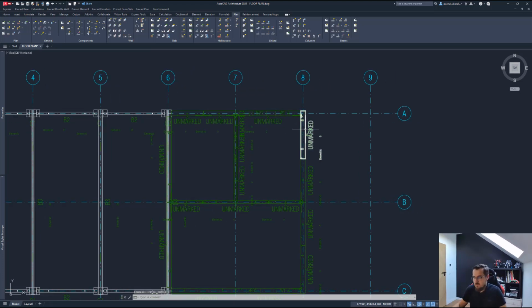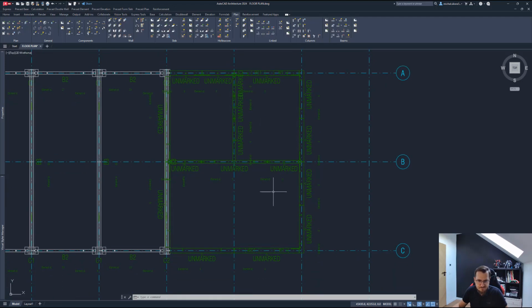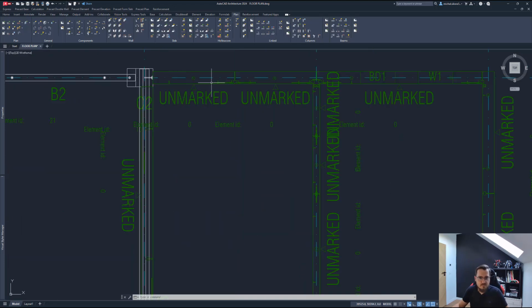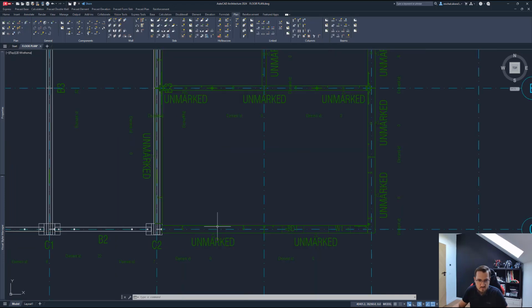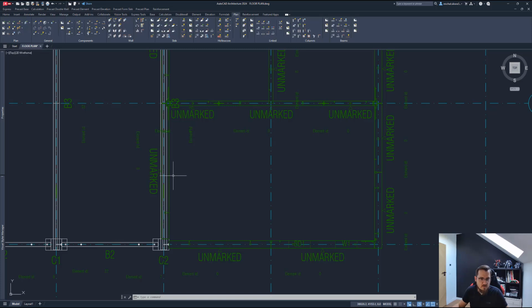What I now want to do is show you the panel thickening, because I want to place some slabs and I want to place them on some panel thickenings. So let's do that. Maybe in this section here. Now too many walls. So let's maybe do that here. Okay. So what I'll do here is I want to create a panel thickening. So I'll just click on this, sorry, not this one, draw panel, click thickening, and I will select an element, right?